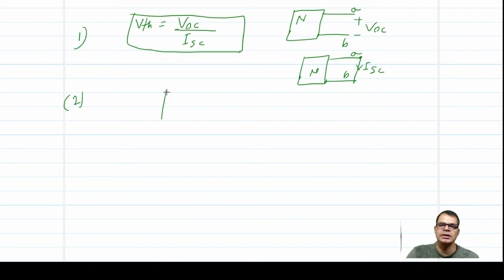Right. Second way is the most widely used, because whenever you are analyzing analog electronic circuits, you will come across many dependent sources like GM VGS, beta IB, GM1, GM2, VGS, VDS, like that. So at that time, what is convenient is, in the network, in one go, just connect a voltage V2 and drive with the I2.